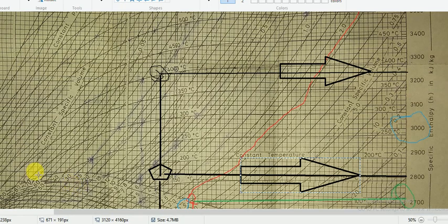The pressure was 30 bar. So follow the 30 bar line, and the temperature was 400 degrees Celsius. Follow the 400 degree line. The point at which the 30 bar line meets the 400 degree line, that is point number 5, that is H5. Move horizontally and note down the value of H5, 3240.